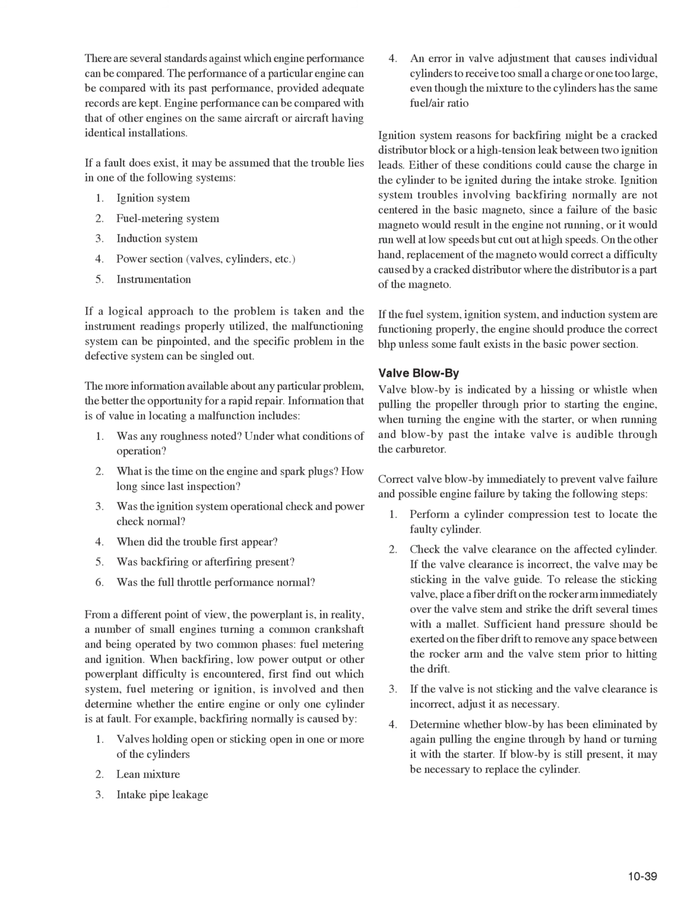3. Was the ignition system operational check and power check normal? 4. When did the trouble first appear? 5. Was backfiring or afterfiring present? 6. Was the full throttle performance normal?